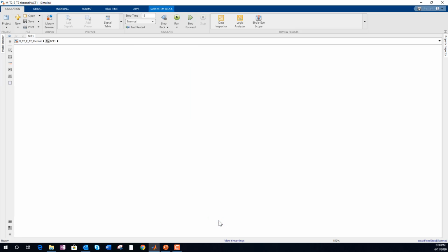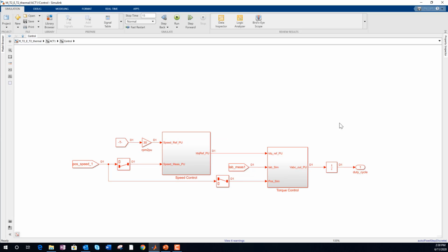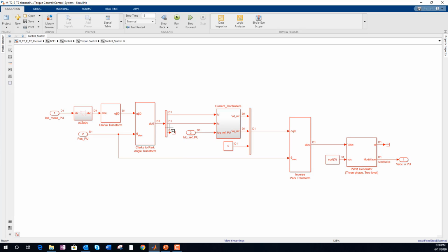On the electrical system, let me just drill into one of the ailerons, the left aileron. We drive the PMSMs with field-oriented control. So I'll just drill into the inner torque control loop here. For those of you who are power electronic engineers, you'll recognize this standard configuration for the inner torque loop, or the inner current loop, for a field-oriented control system.